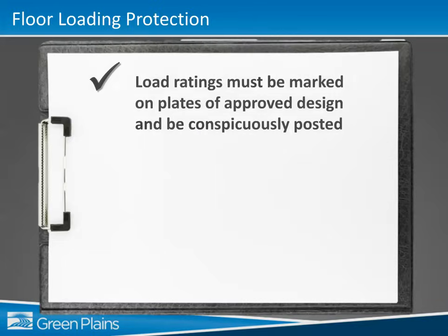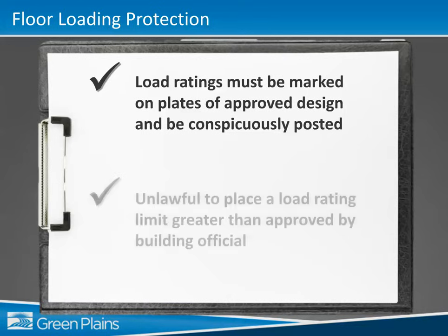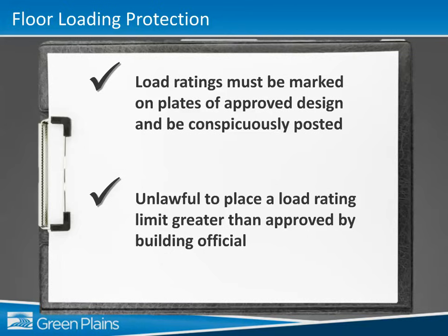Designed floor load ratings must be conspicuously posted where items are stored. It is unlawful to place a load rating limit exceeding the limit which has been approved by the building official.